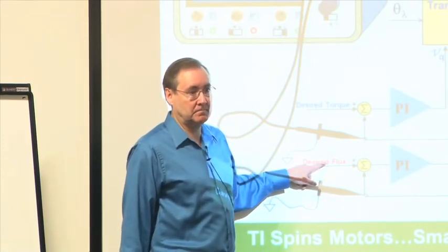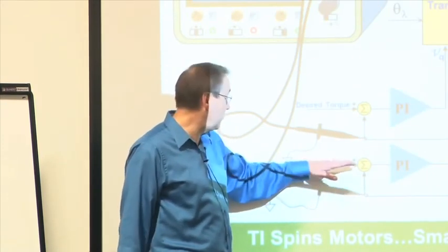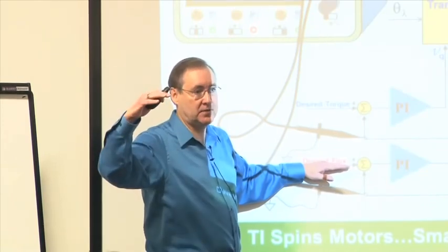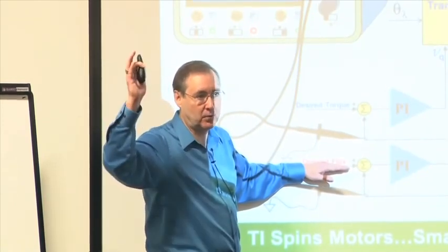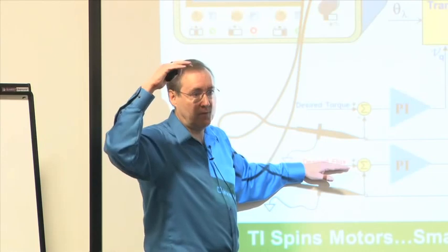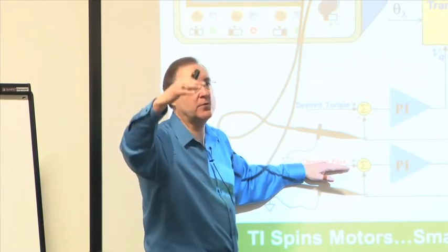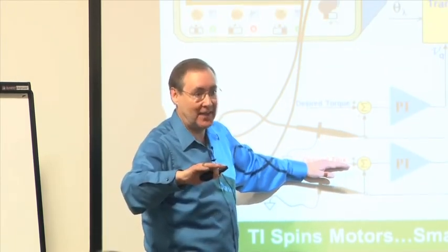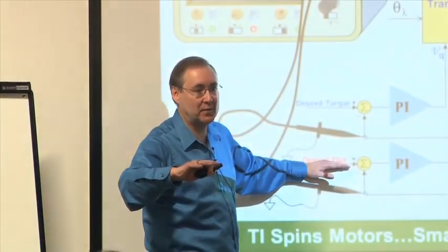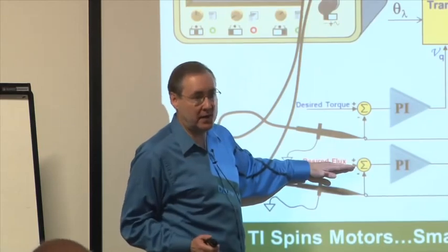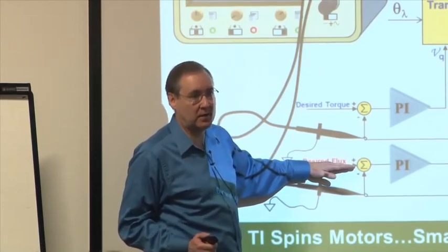When you slip in your motor, you start giving that a value. Yes. Well, actually, the motor will have a rated flux. It'll say, okay, it wants to work at this flux if it's 60 hertz or 50 hertz or whatever it is. For the voltage that it's rated at, you can say, okay, this is volts per hertz. It's like 430 volts at 60 hertz. That's rated flux. That's another dimension for flux, is volts per hertz, if you go through and work it out. So I know what that will be then, and I can set that motor to work at that rated flux.